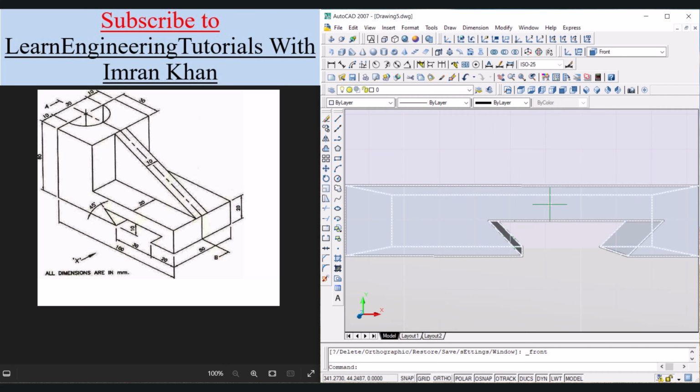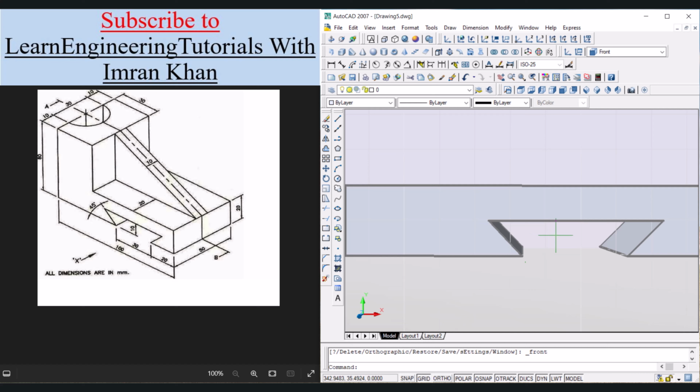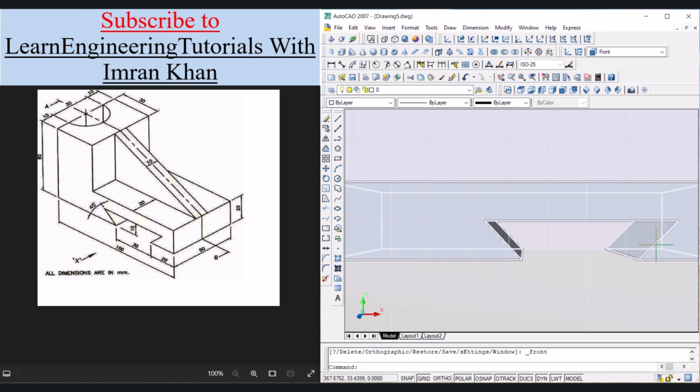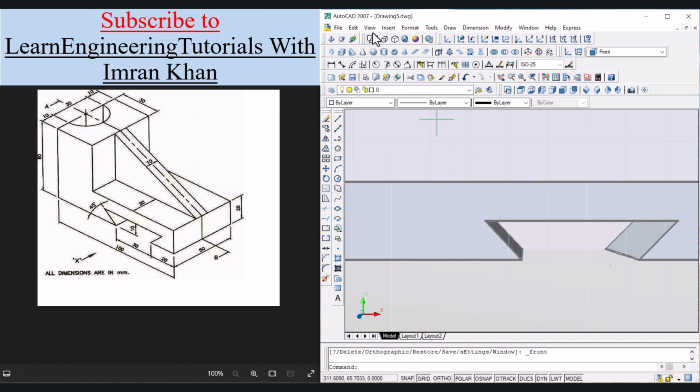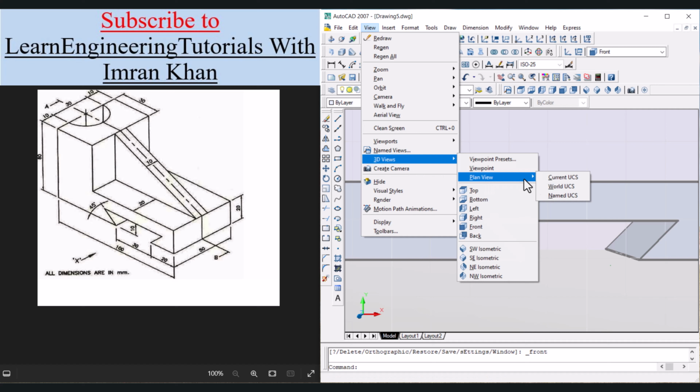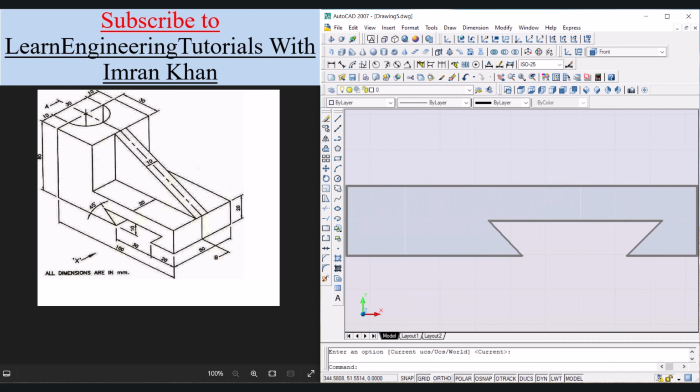Now this object looks okay from a human perspective or camera perspective, but we can see that this line where the cursor is, this should be parallel to this line, and these two lines should be one after the other. So we should not see this area, but here we can see this area. So because the plane view or orthographic view is not selected, for that we have to go to view, click on 3D views, and click on plane view, and here we can click on current UCS, and now we can see that the object looks okay from orthographic point of view. Click on SE isometric icon.